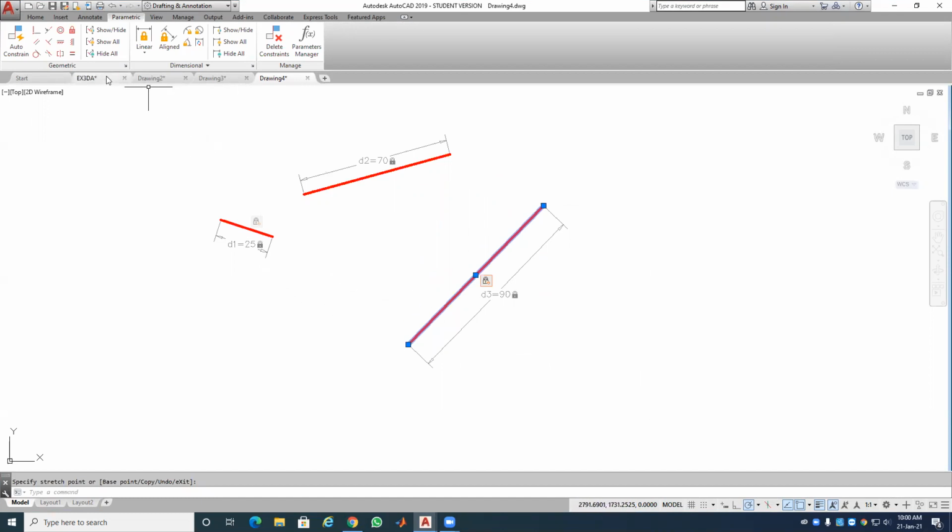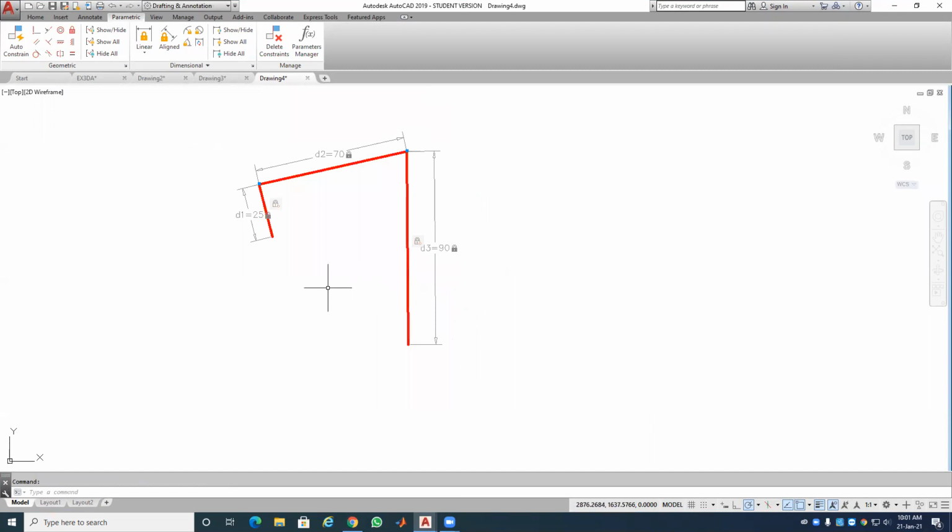What I'll do next is connect all these three using this coincident. Coincident that with this, you have this blue dot, meaning that is the hinge or the pin joint, and let's connect that to that. Now I can click here and turn this machine back and forth, back and forth.